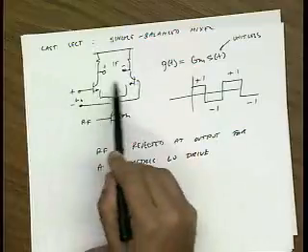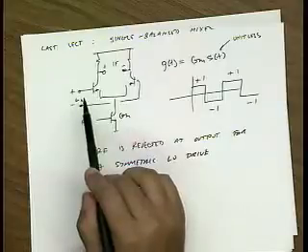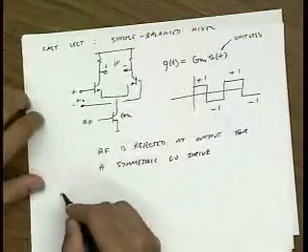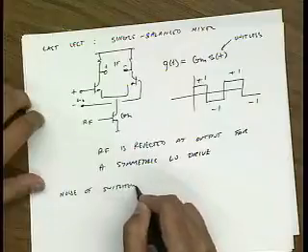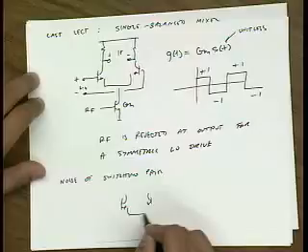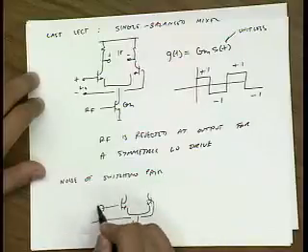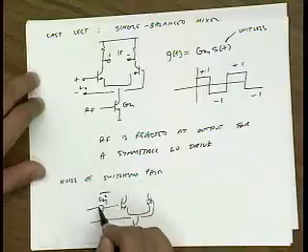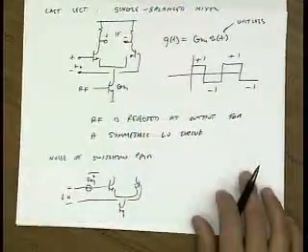The switching pair, this is not a noiseless differential pair. It has noise in it, right? So the equivalent circuit is as follows. Basically, there's a noise, V equivalent, in series with our LO.